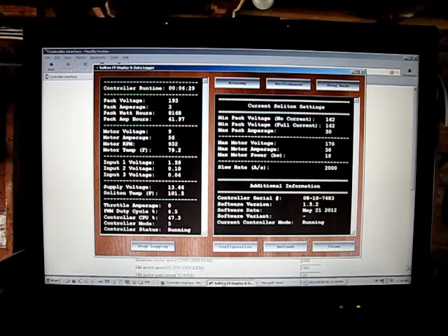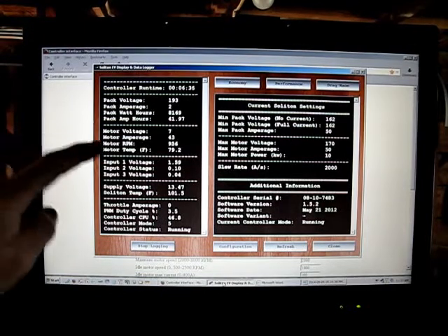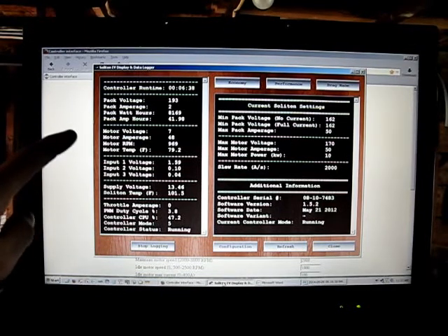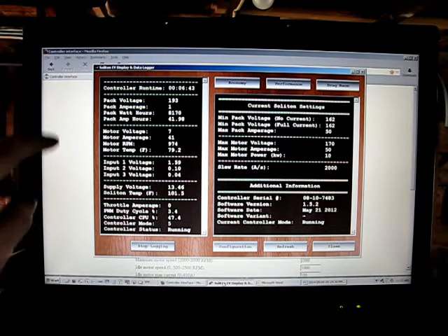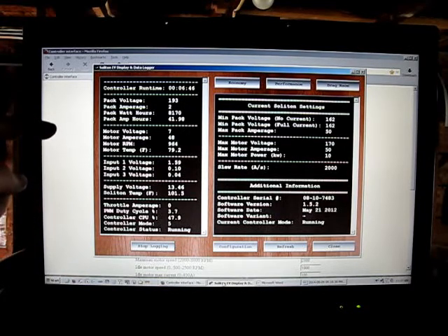So it's still limited to 50 amps for the maximum motor current, but now we've set the idle current to 100, which is kind of weird because it can't get there. But that seems to allow the motor voltage to rise up to the point where it can hold that RPM properly. I'm not really sure why.